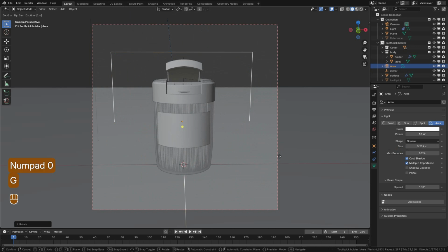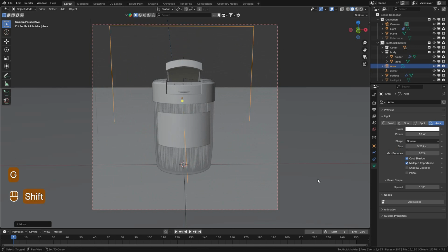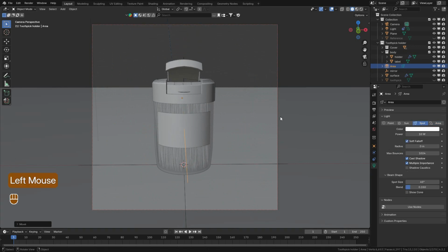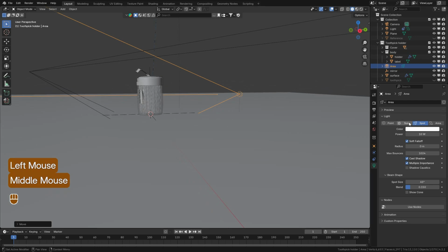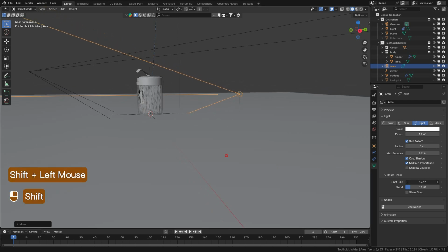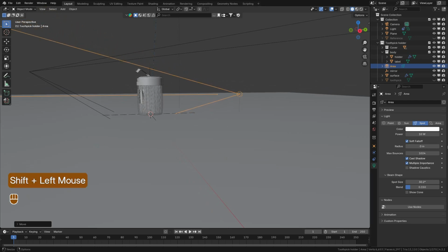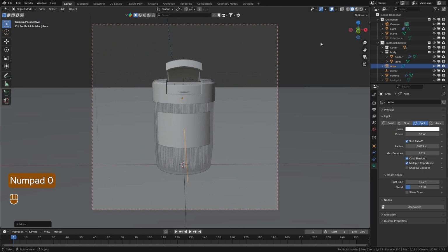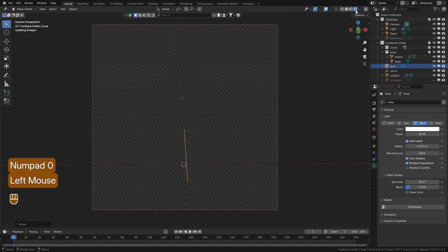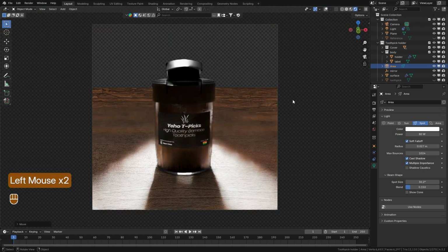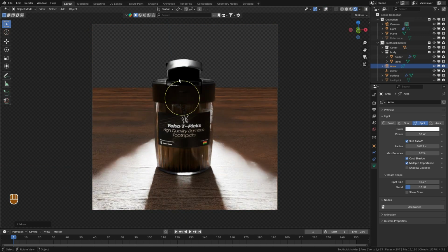Go to our front view, bring it up. Want to make sure it's a spotlight. Reduce our spot size, increase our radius a bit, and you can increase this to maybe 80 watts and then see where you go from here. Go to rendered mode. This gives us some sort of a nice look.